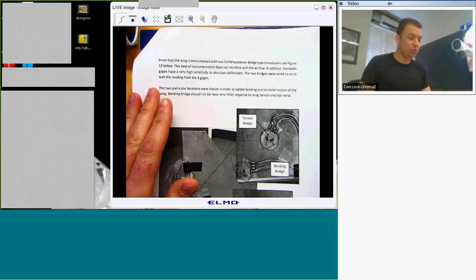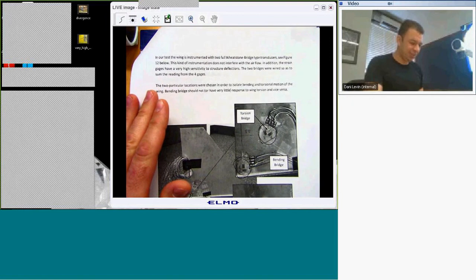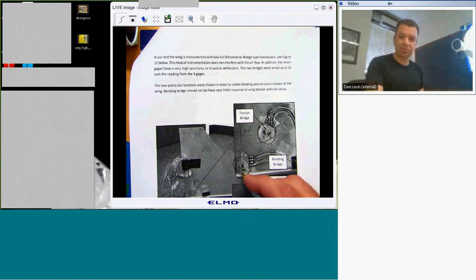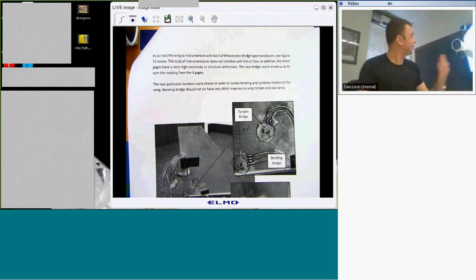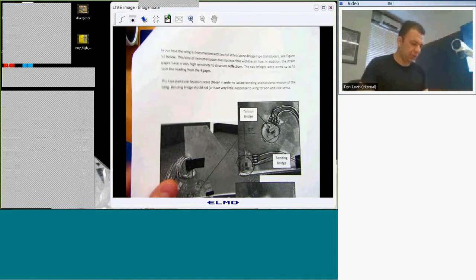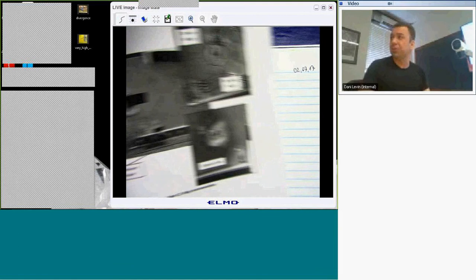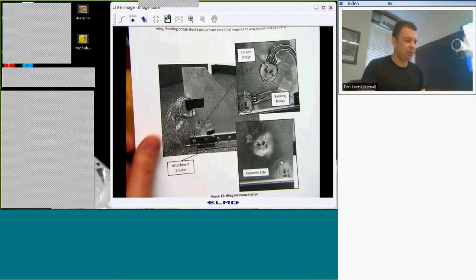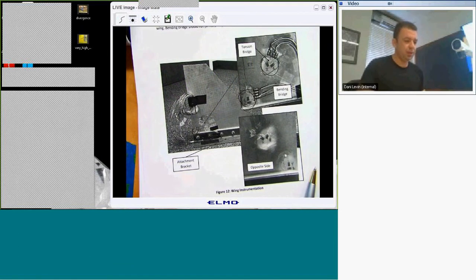I'm actually using 4 every time. These are 2, and we have the complementing couple on the other side. So it has to do with the Wheatstone bridge. In every instrument that reads strain gauges, a Wheatstone bridge is implemented in one way or another.